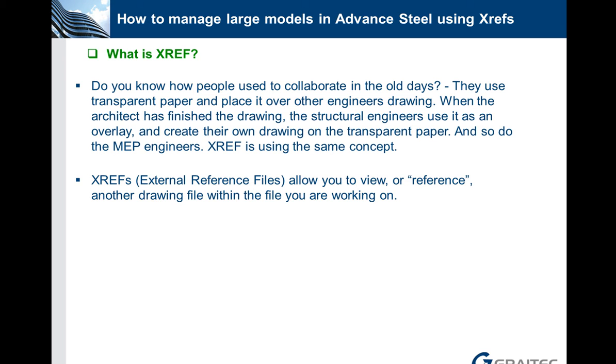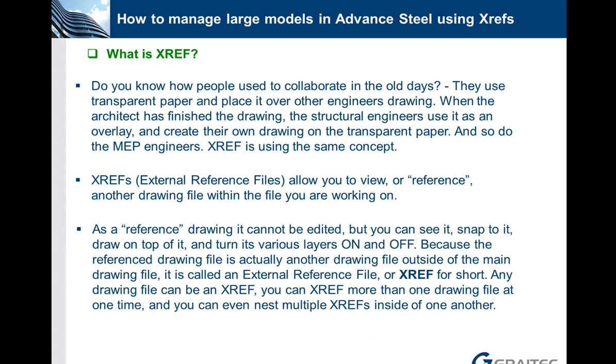XRef allows you to view or reference another drawing file within the file you are working on. As a reference drawing, it cannot be edited, but you can see it, snap to it, draw on top of it, and turn its various layers on and off. Because the reference drawing file is actually another drawing file outside of the main drawing file, it is called an external reference file, or XRef for short. Any drawing file can be an XRef. You can XRef more than one drawing file at one time, and you can even nest multiple XRef inside one of another.